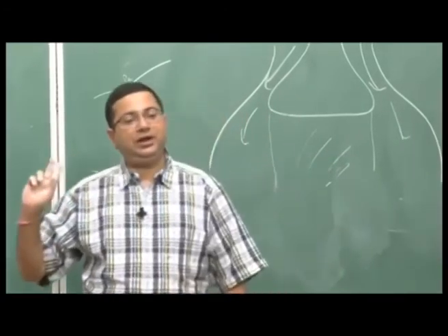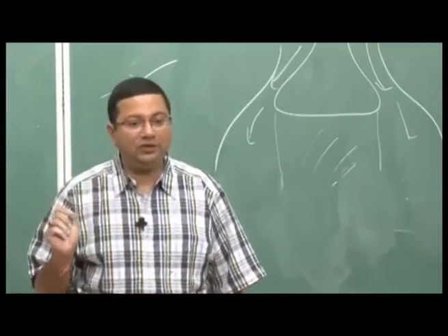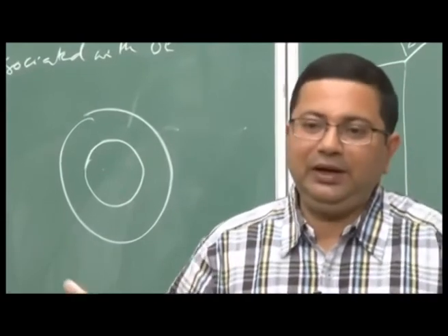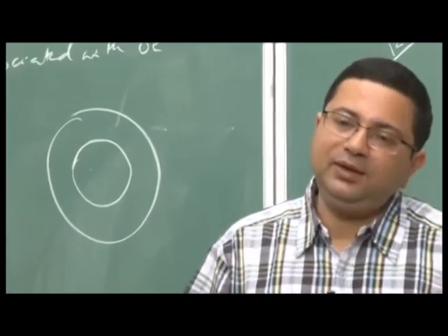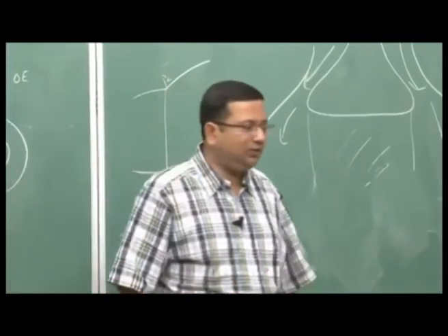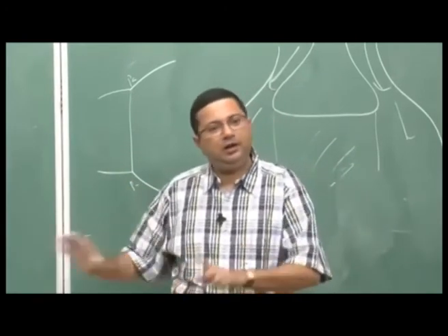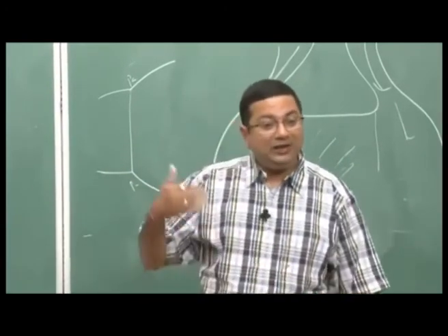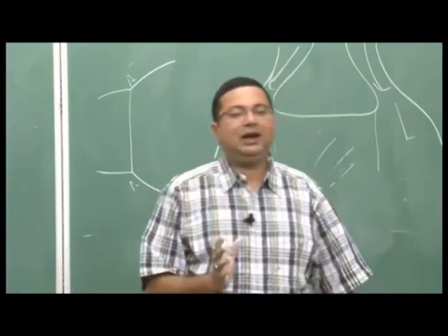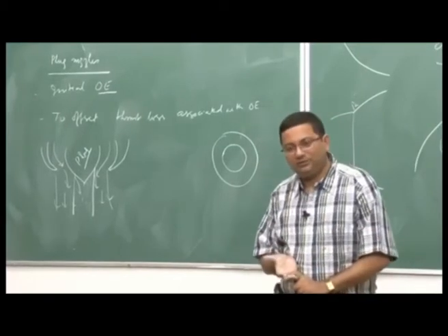Another parameter which we had discussed during the performance of chemical rocket is characteristic velocity, and we have shown that the Isp, which is the final important parameter for us, is the product of these two, or thrust is the product of these two, thrust coefficient and characteristic velocity. So, now I think we should have a fairly good handle on the thrust coefficient. So, next what we are going to talk about is the characteristic velocity. We have shown that the characteristic velocity depends on chamber pressure and chamber temperature.